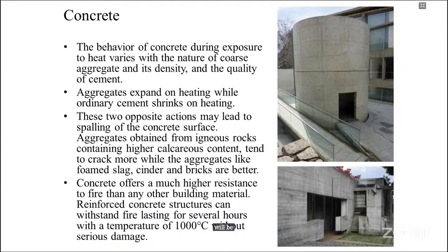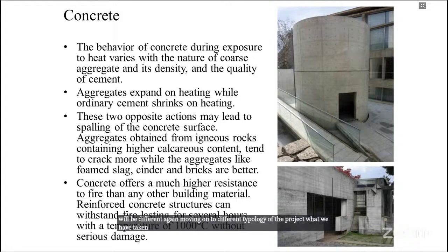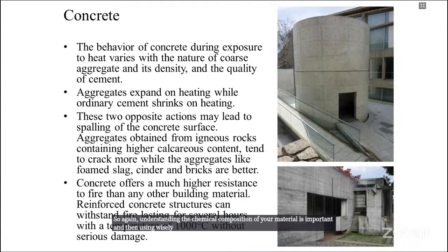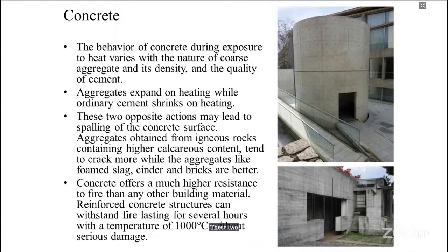Again, moving on to the different typology of the project we have taken. Aggregates expand on heating while ordinary cement shrinks on heating. So again, understanding the chemical composition of your material is important, and then using that material wisely in your building is an essential part of a designer's job. These two opposite actions may lead to spalling of the concrete surface.